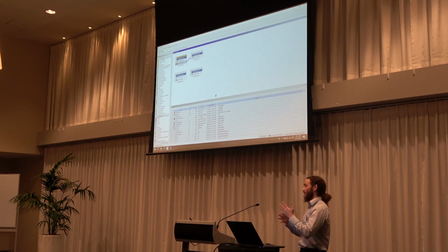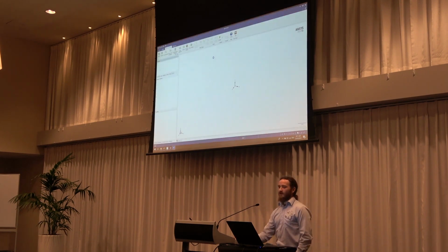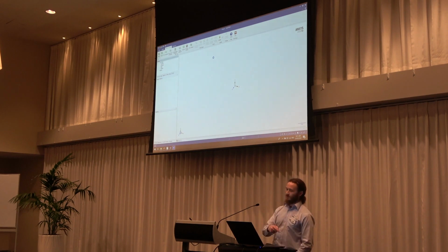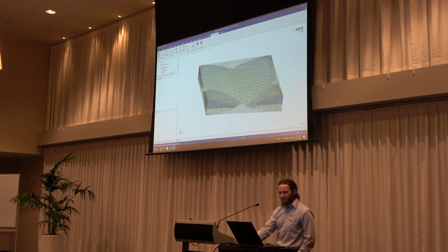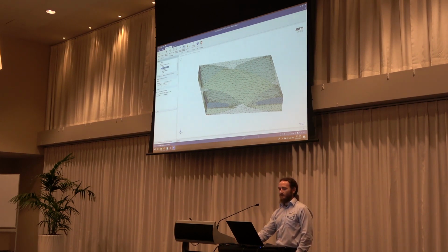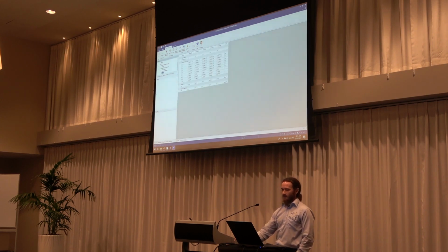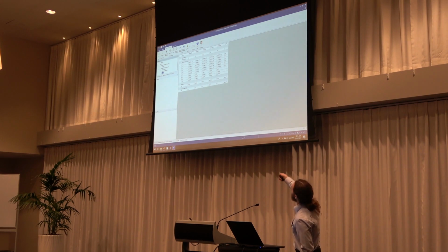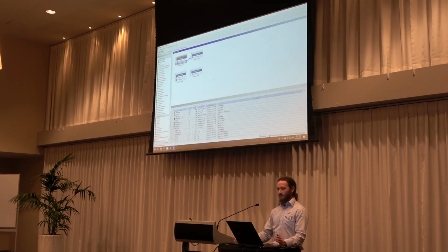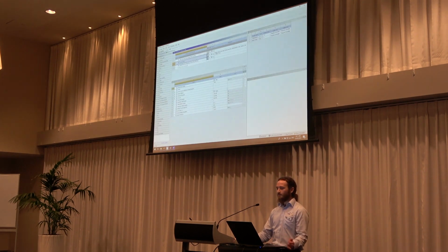Other flat parts, I'll have a zero shear angle. So I need to be able to tell ACP what the mechanical properties for that are. In this case, I've done a variable material evaluation between 0 and 20 degrees at 5 steps. I've solved it, and then we look at the results, and you can see we've got the material properties for all those different angles. And then if we go into engineering data,